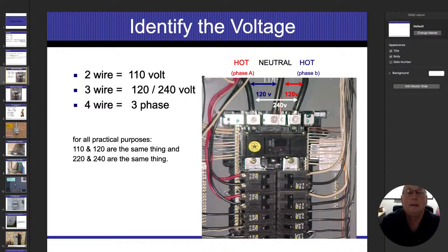One thing that I get asked a lot. Now, this breaker just has 1 switch on it. But sometimes we'll see a 2-pole breaker. And if you look at the 240 circuit on the left side, it looks like it's on the right side as well. But either one of those, we're going to have a bar that ties the 2 of those together. And let's say each one of those is 30 amps on each one of those switches or breakers. And what we don't do is we don't add them up. So if it's 30 and 30, that doesn't mean that it's a 60 amp circuit.